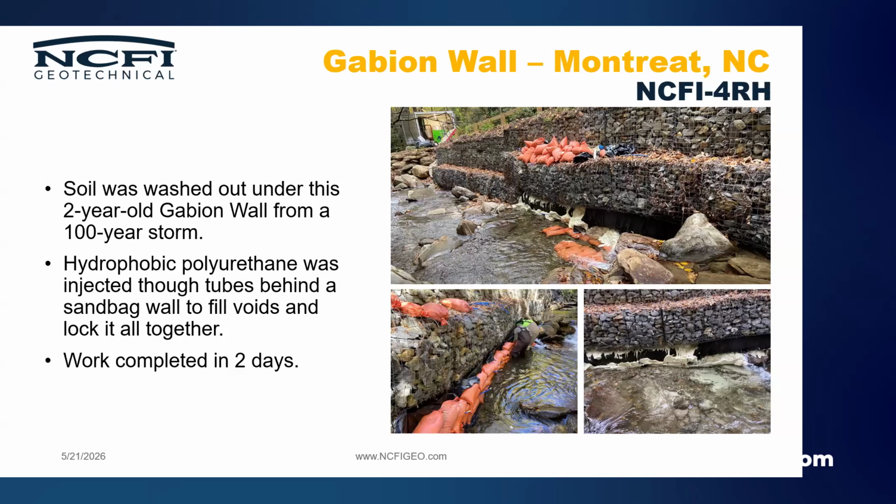And so we went in and put the sandbags in, used PEX tubing, pushed it to the back, started at the down creek side so that any water that was still getting back there would just push the foam towards the end instead of it potentially messing up the flow, and filled up all of it. Bottom right is your final picture.